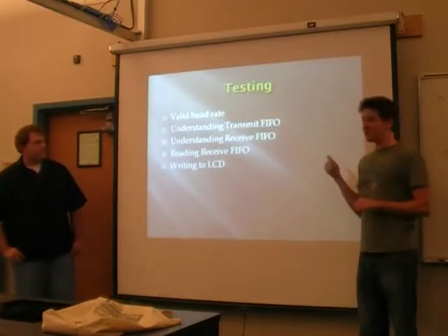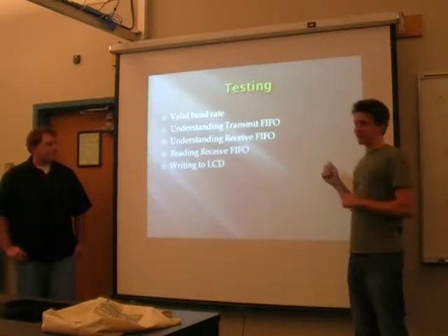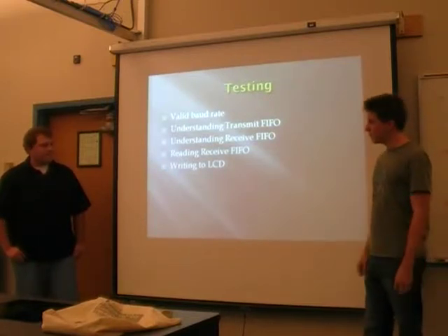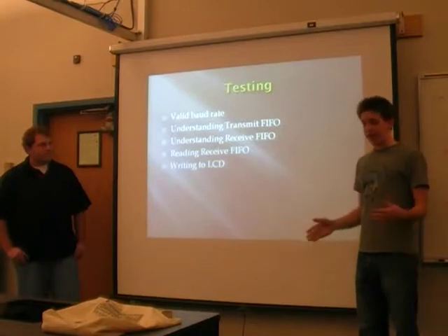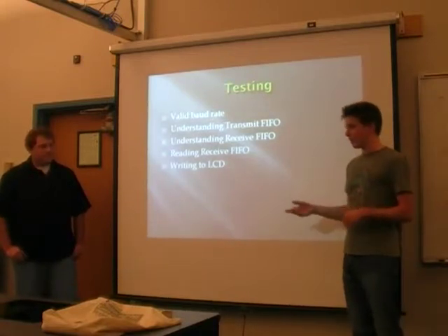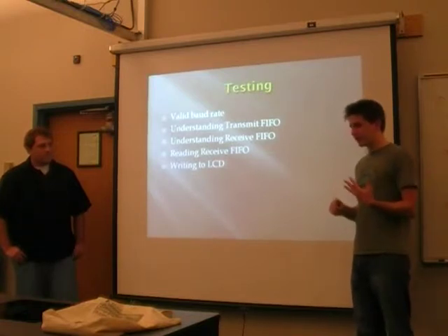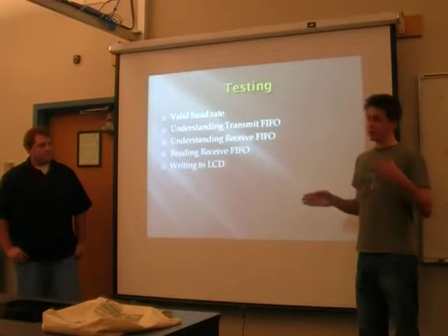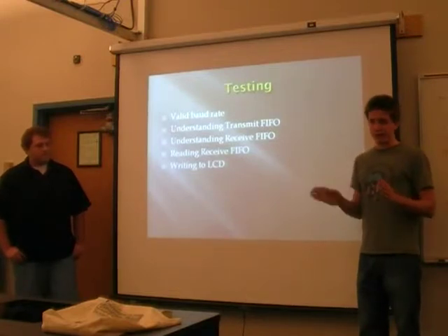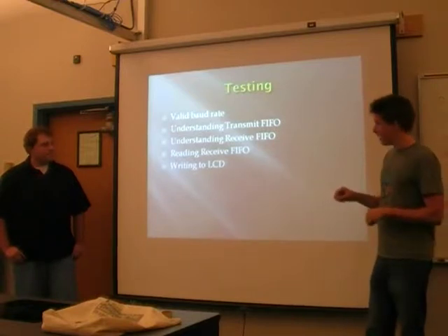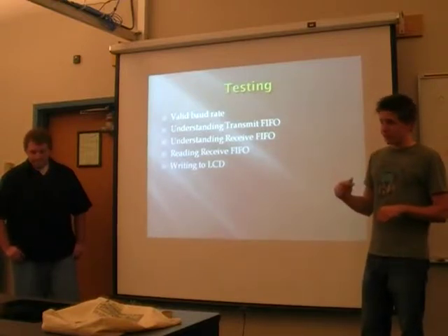As I said earlier, understanding the valid baud rate was the hardest part of our testing. It took the most time. And even though we were never actually transmitting to the keyboard to tell it to turn on the number lock, scroll lock, caps lock LEDs, we still needed to make sure that the FIFO was reading at the right rate, sending at the right rate. And so we had it turn on the LEDs.